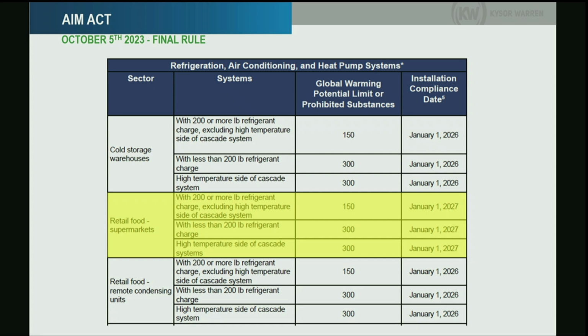You know what's the limit right now? For California, 150, if you have more than 50 pounds of refrigerant for new systems. Well, that is California. Everywhere else, they don't have a limit for that. You can still install 448, 449 in other states, but not in California. This year we will see changes. Well, also for condensing units, they have a limit that will be 2026.